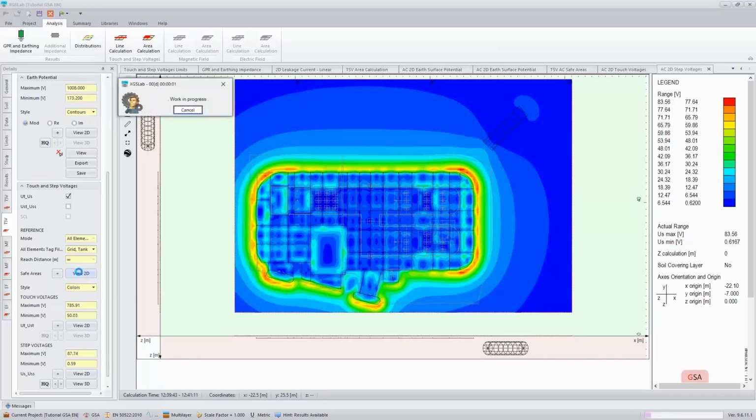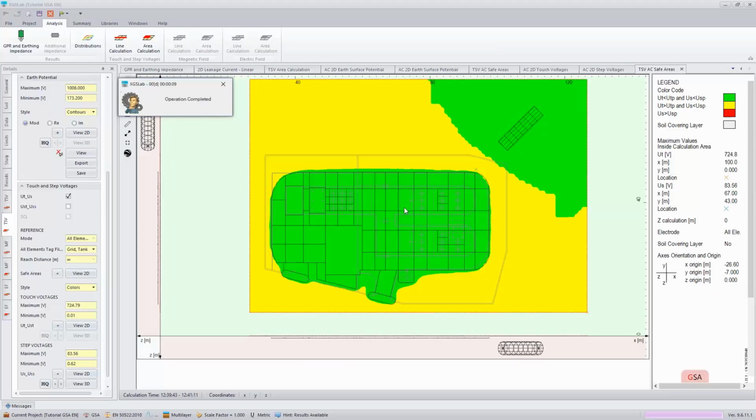What we'll find is a different plot for our permissible limits, because the voltage of the Earth's surface relative to our substation, when you're within the substation, is acceptable within permissible limits. And when you're close to the tank, the difference between the tank's voltage and the Earth's surface potentials is within the permissible limits. We'll go ahead and take a snap of this for our report.